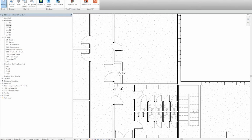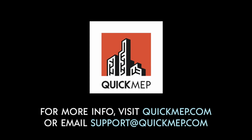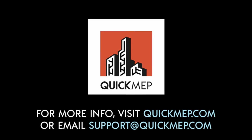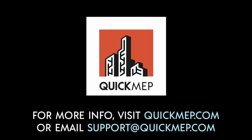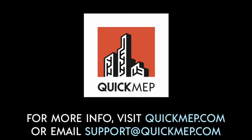So to summarize, the purpose here is to use this as a jumping off point for your projects and to save time getting your models set up. This takes advantage of the Revit API to get your distribution system set up and to get all your voltage definitions input, and all of this is modifiable once it's done, so it gives the user full control over the final design. But hopefully it saves you some time getting your project set up.